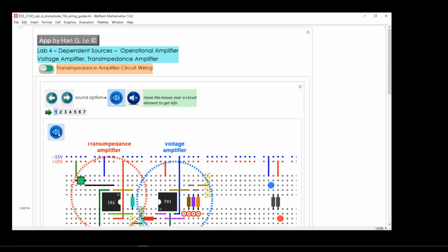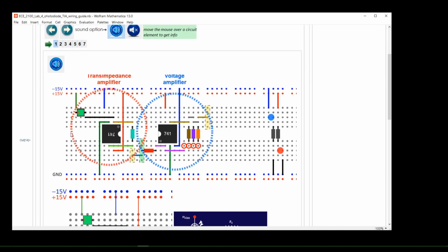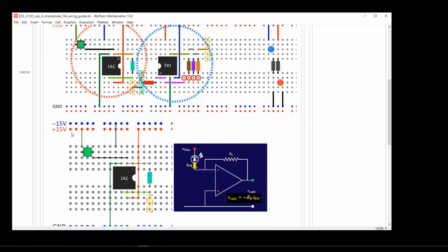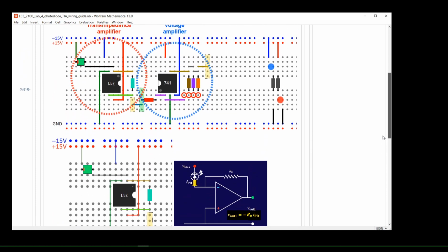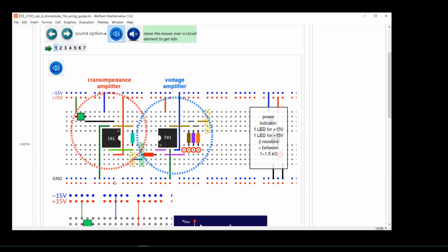This circuit is to be used with the voltage amplifier of Part A. Hence, the relative position of the circuits with respect to each other on the breadboard should be taken into consideration. On the left-hand side is the circuit to be built. Notice that pin 6, the op-amp output, should be coupled to the 1 kΩ input resistor of the voltage amplifier on the right. The op-amp orientations are upside down with respect to each other. This can be changed, if one is concerned with the habit of wiring to the power supplies. Caution should be exercised. Next, when ready.